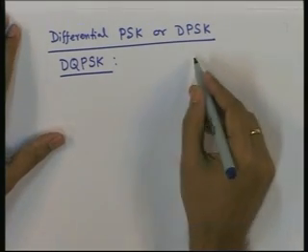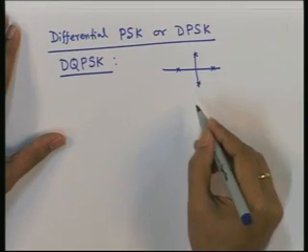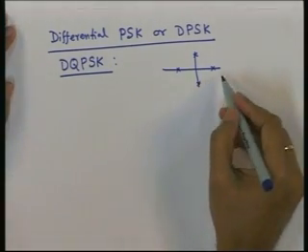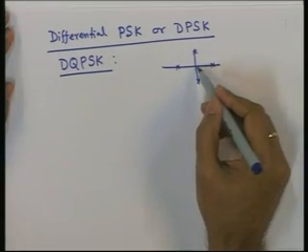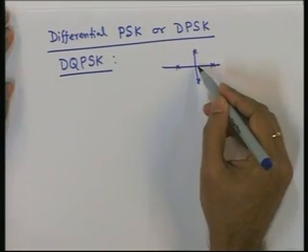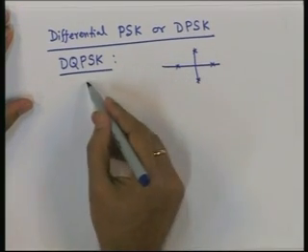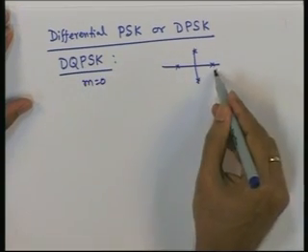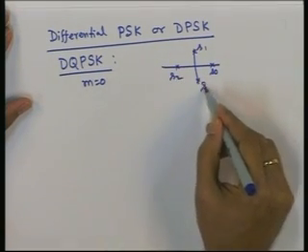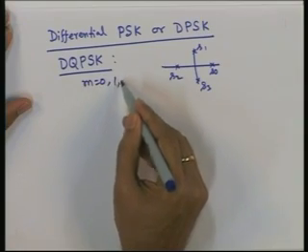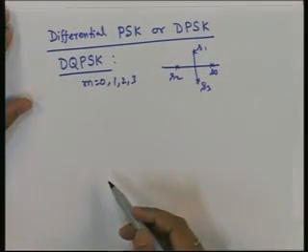So we have the QPSK constellation, and traditionally what we do is we encode the 2 bits into one of these points and transmit. That means the actual phase of the signal that we transmit depends on what bits we want to transmit. If we want to transmit, say, m equal to 0, we will transmit this point, this is S1, this is S2, this is S3. So m equal to 0, 1, 2, 3. For each, we will transmit the corresponding point.